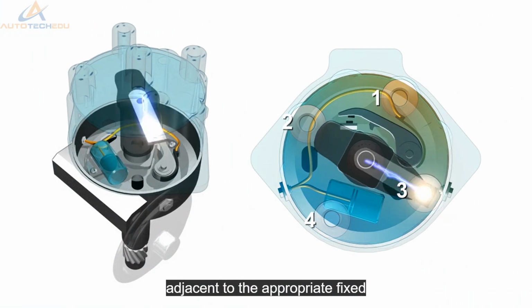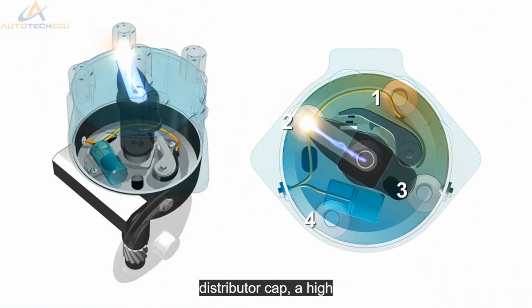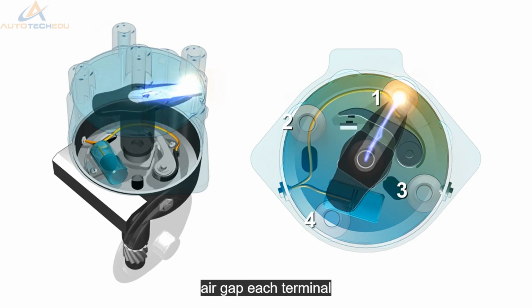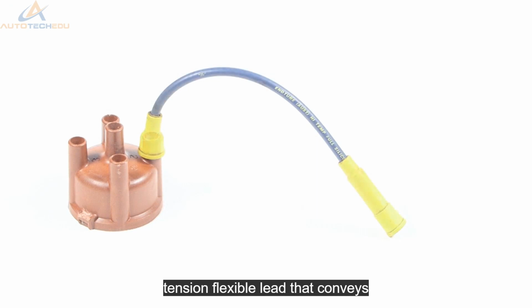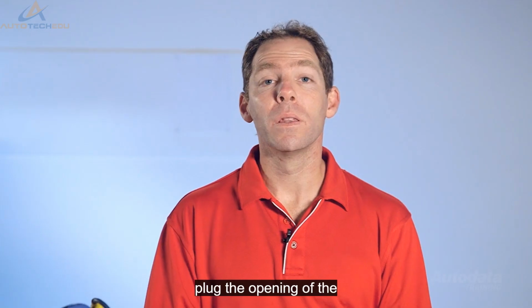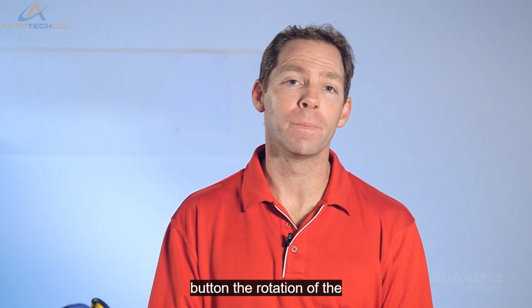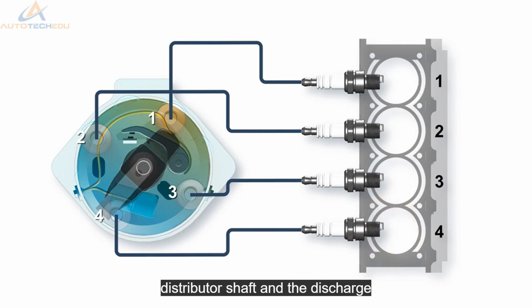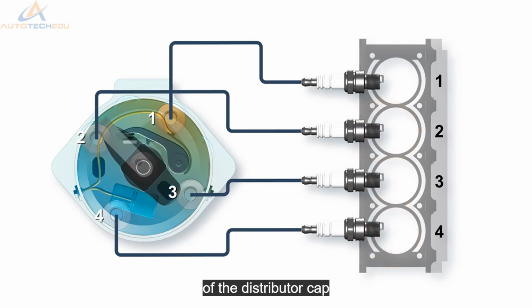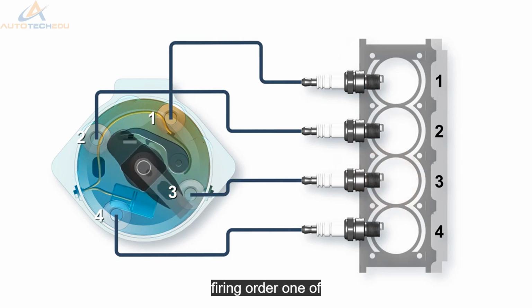When the button is adjacent to the appropriate fixed outer electrode in the distributor cap, a high voltage charge will jump the air gap. Each terminal is connected to a high tension flexible lead that conveys the current to each spark plug. The opening of the contact breaker is timed to the position of the rotor button. The rotation of the distributor shaft and the discharge of energy to each terminal of the distributor cap must correlate with the engine's firing order.